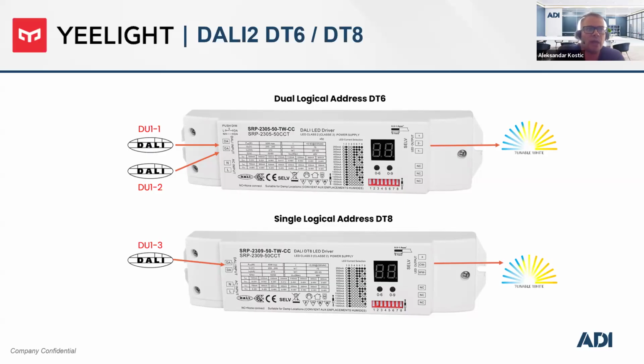There we differentiate two main types of the DALI drivers, DT6 and DT8. The main difference is in the number of addresses they use. DT8 is more advanced because DT6 uses one address for each parameter control. So if we are using a control of tunable white, one address will be used for control of the brightness and the other for control of the temperature, while DT8 uses a single addressing per load, and due to that it needs less addressing and has more advanced, more effective communication.